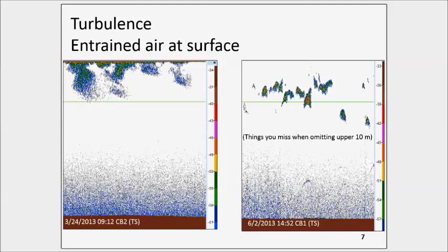Short pulse durations will increase the resolution of your data, as well as lower the total energy that you're putting into the water for any single pulse. So that is also going to maximize your signal-to-noise ratio around these features, only because you won't be getting the return as much from a longer duration pulse.